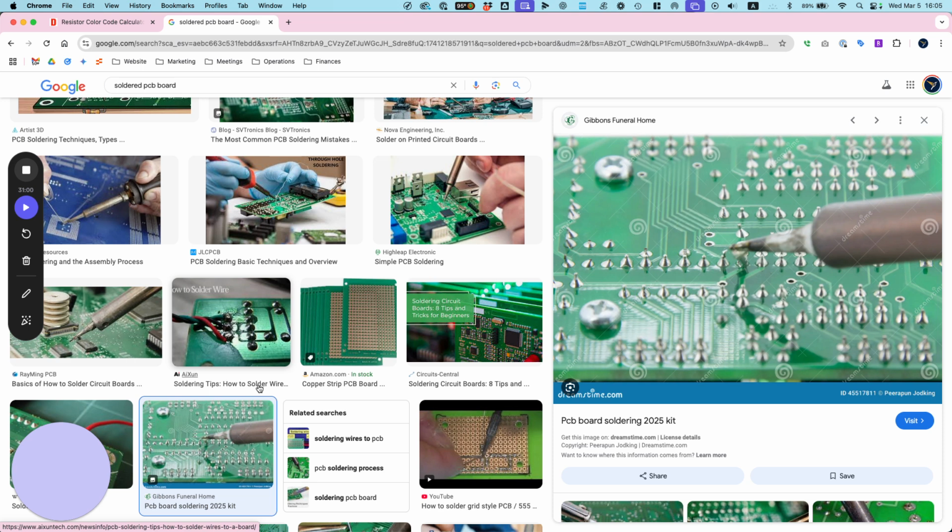So you can see that there's actually 3 ports down here. This COM is always going to be the black. When you want to do current, that's when you need to switch here. Everything else you see is voltage, resistance, frequency. You can do milliamps, so like little current. But if I turn this back on again, look at my system here and tell me how many amps we have.